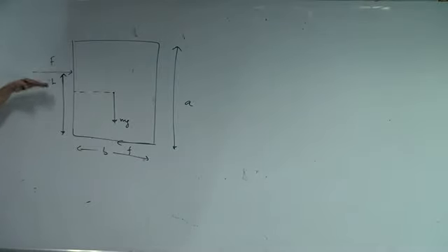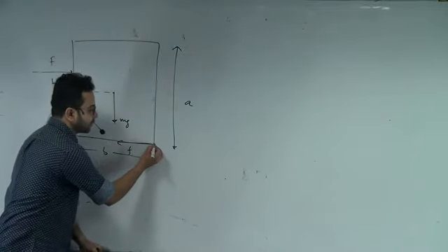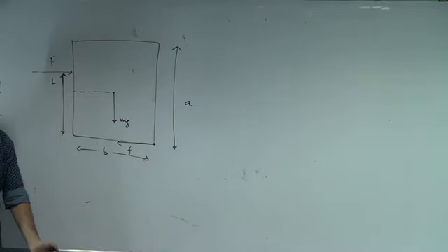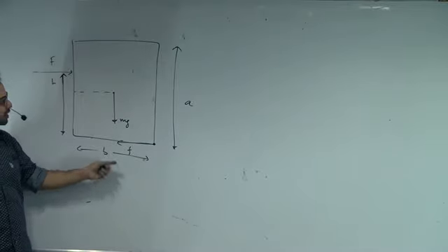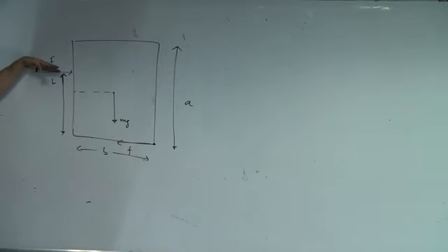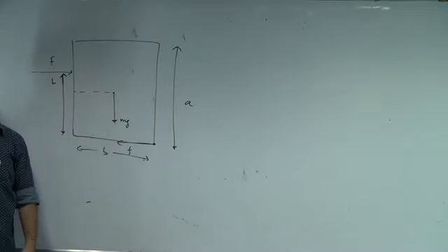Now we are talking about the torque from this point. If we are talking about the torque from this point, the torque of friction will become 0. Now realize that mg will have a constant torque. How much? mg multiplied by this distance, that is b by 2. Now what will be the torque of force F about this point? F into h. If I increase the height, the torque of the force becomes greater, so this will have a greater tendency to topple.